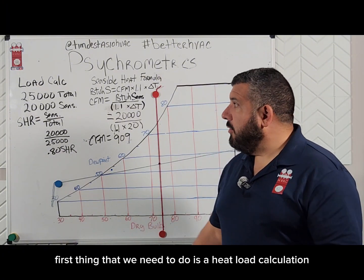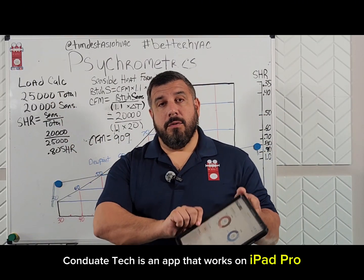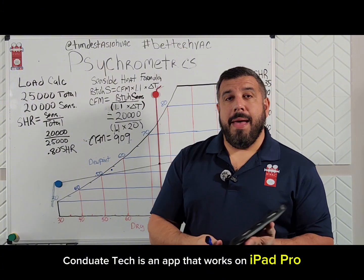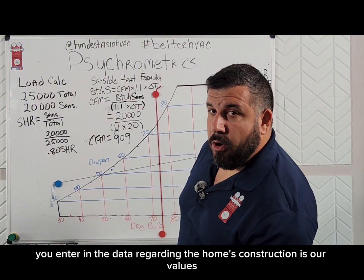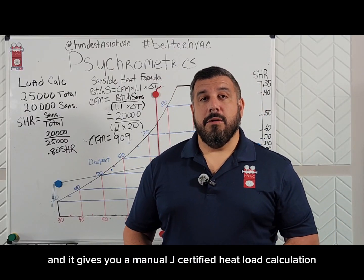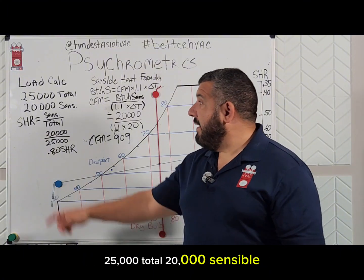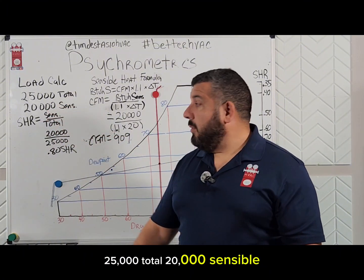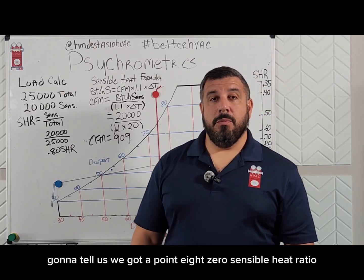The first thing that we need to do is a heat load calculation, and for that, I use Conduit Tech. Conduit Tech is an app that works on an iPad Pro. You scan the house and you measure it. You enter in the data regarding the home's construction and its R values, and it gives you a Manual J certified heat load calculation. Let's say that when we do that, it comes up with these numbers right here, 25,000 total, 20,000 sensible. It's going to do the math for it. Conduit Tech's going to tell us we've got a 0.80 sensible heat ratio.